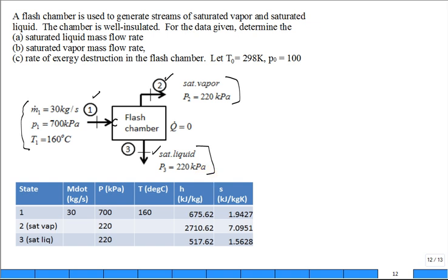Basically, there's a restriction right here, the pressure drop. You use the presence of gravity to collect the liquid on the bottom and the vapor on the top, and you extract the vapor off the top and the liquid off the bottom. It's saturated inside, okay? This is not a complicated device. Why do they call it flash? Because some of it flashes to vapor, but most of it still remains.